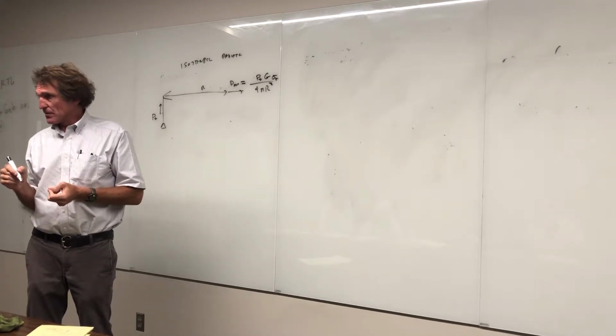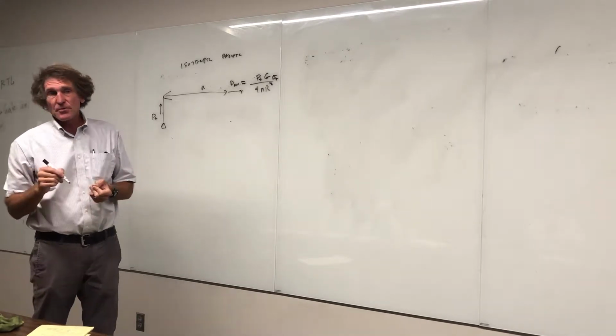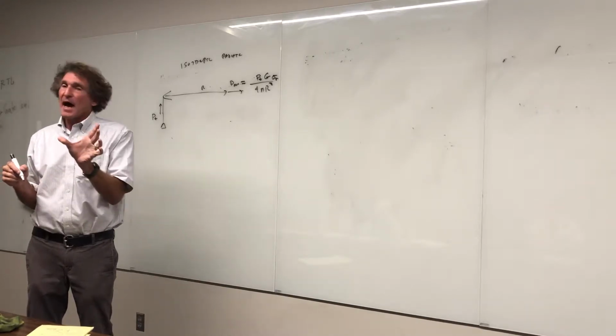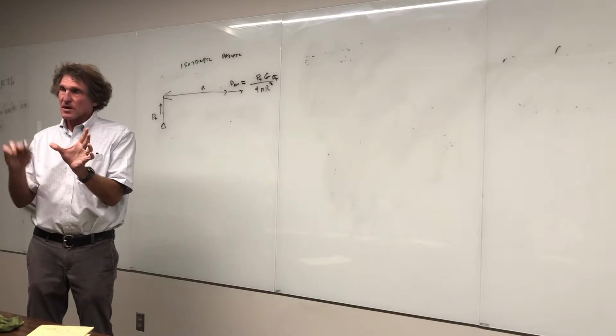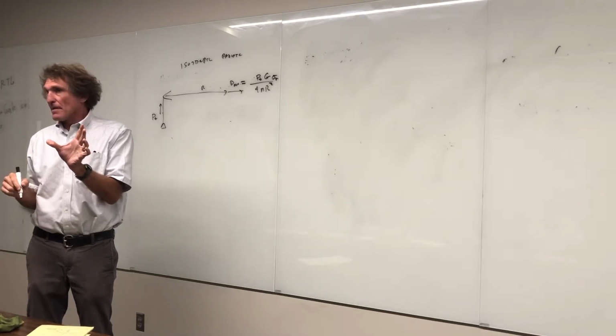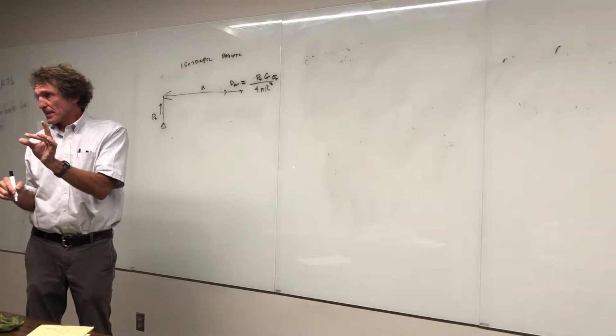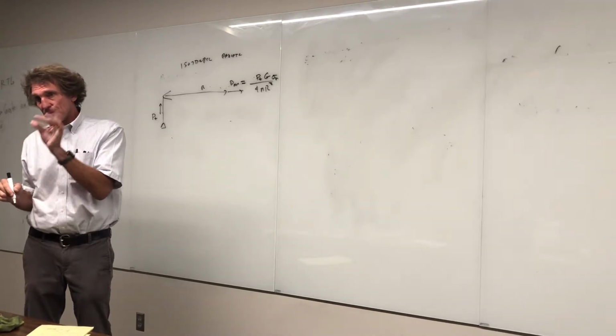They give that to you if you buy an antenna. And they'll also talk about the actual beam width. And the beam width is how wide the first lobe is. This comes a little later. It's beam width in an antenna. The higher the gain, the narrower the beam width of the main beam. Follow me? It's one of those things that happens.